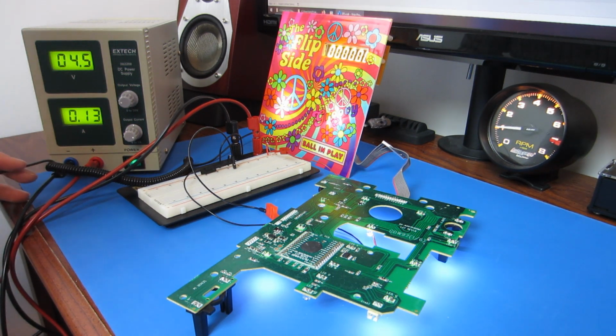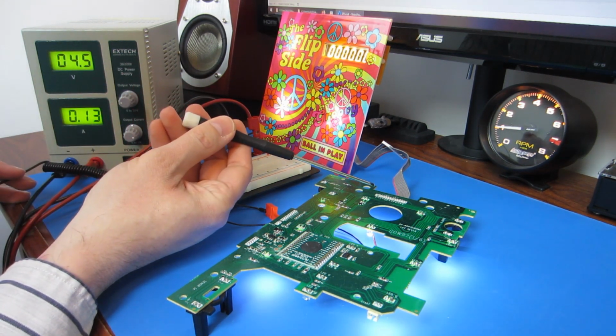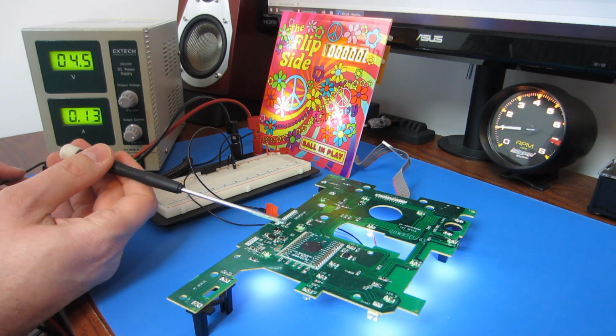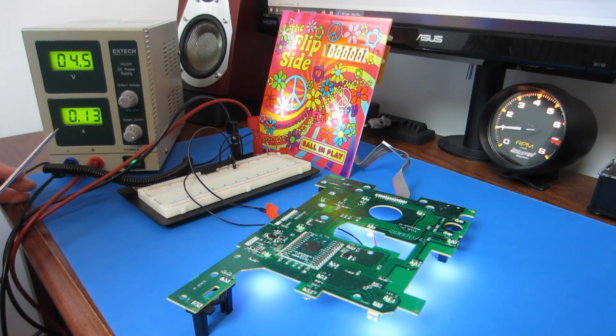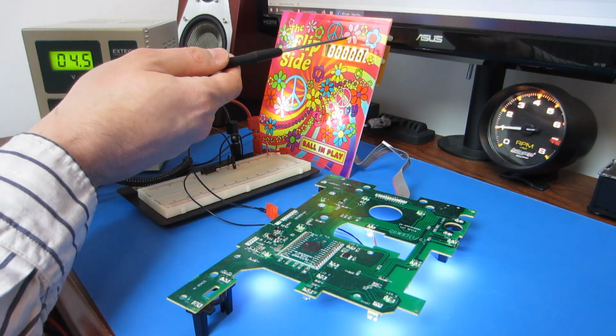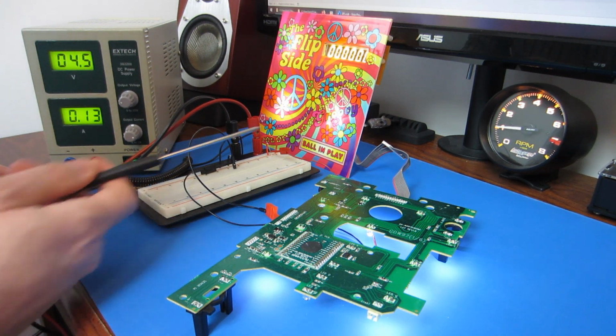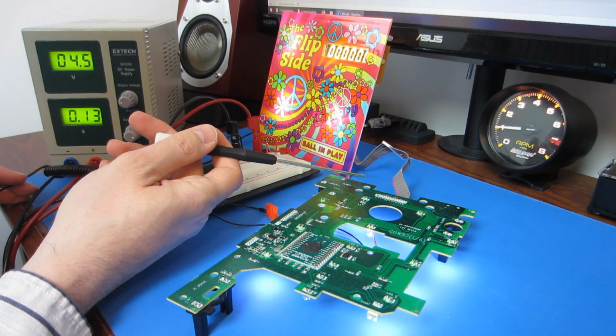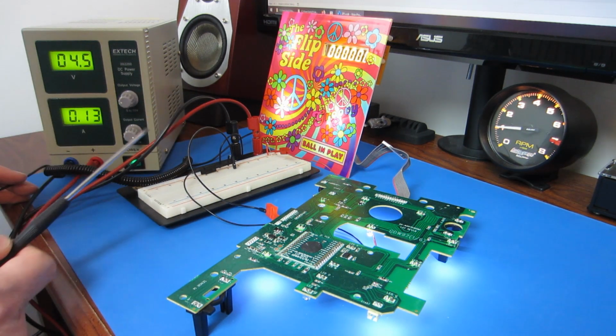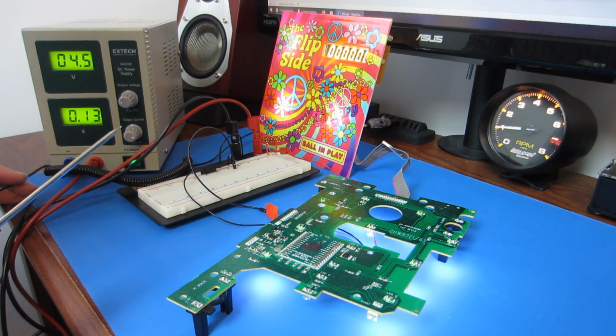So my goal is going to be to tap into the SPI pins there while the microcontroller is communicating with the backbox, and maybe activate some switches and get this score to change and see if I can see, well, number one, see if I can see any data on that MOSI pin, and then see if I can see the data changing when I activate switches and get the score digits to change.